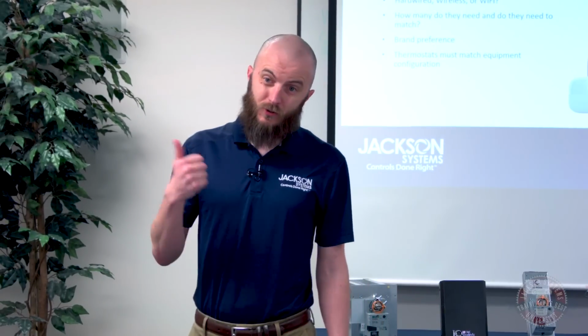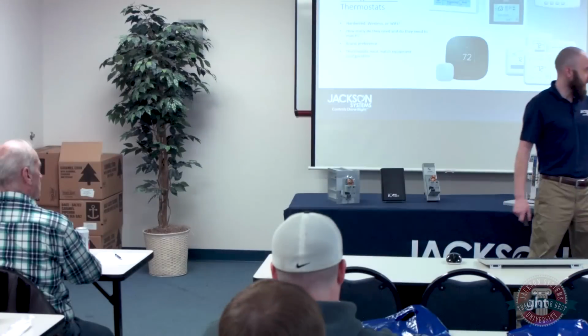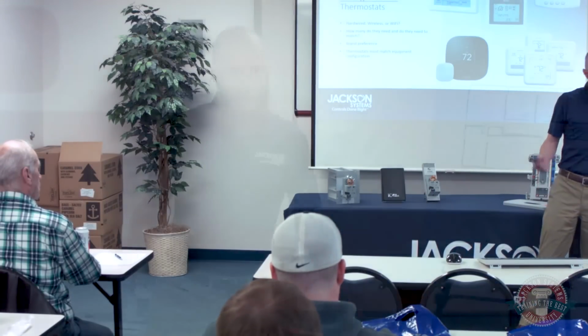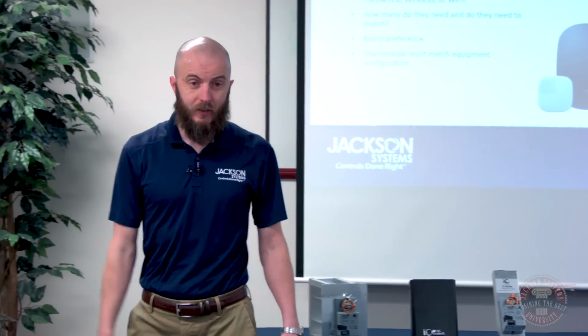So some of the questions you need to talk to your customer about and the things you need to look at when you're laying out the system. One, do you need hardwired thermostats? Do you need wireless thermostats? Do you need Wi-Fi thermostats? Depending on where you're wanting to place the thermostats in the house, some may be more accessible than others. If it's not going to be convenient or even possible to get wire pulled from one area where you want a thermostat to where the zone panel is going to be, then you may need to have a wireless thermostat. And most wireless thermostats will work just fine with most zone panels.